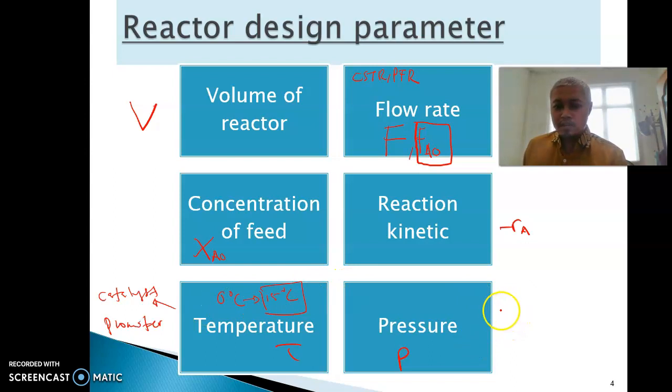The same goes for the pressure. For pure CO2, we need to have pressure around 36 bar. But if we have a promoter, the pressure can go down to 32 bar. So we don't have to have high pressure to produce CO2 crystals, because pressure is equal to the amount of CO2 inside the reactor, which means at 36 bar, we will have more CO2 concentration as compared to 32 bar.